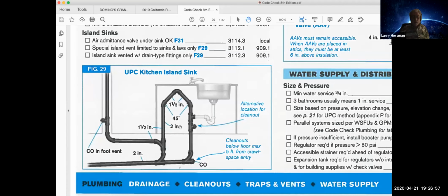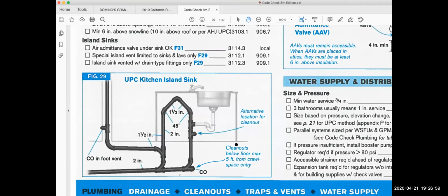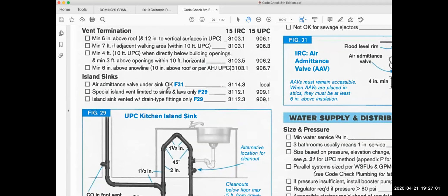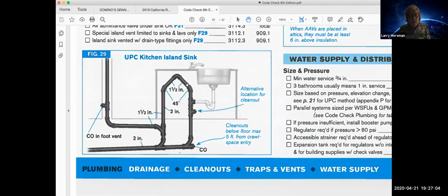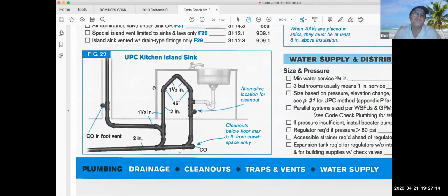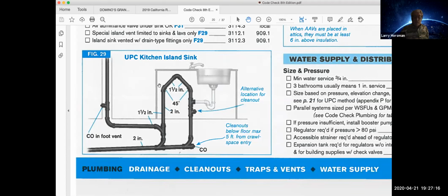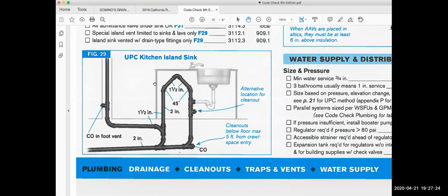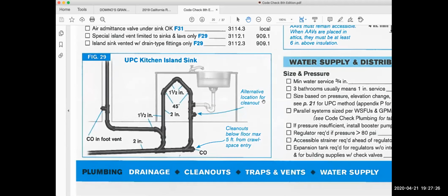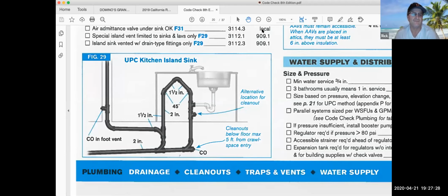And I don't know if they've got the IRC, it allows a little simpler. They just let you come up with a 90 here and a 90 over here, and they have a straight piece of pipe in between them. So the plumbing is a little simpler for the IRC where that's enforced. So hopefully you have enough air pressure pulling from the regular vent to pull all that air that's trapped up in there out.